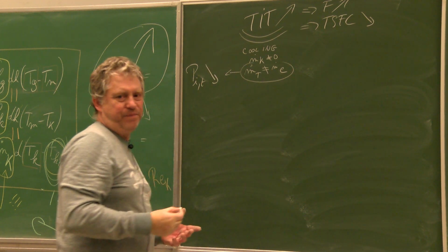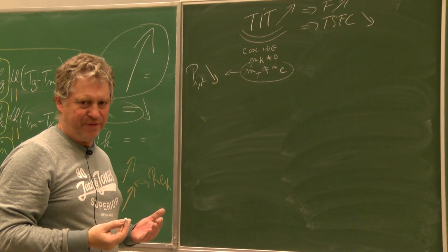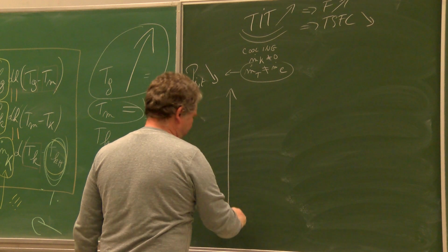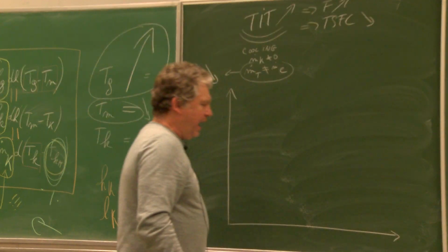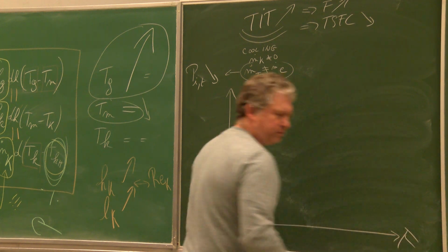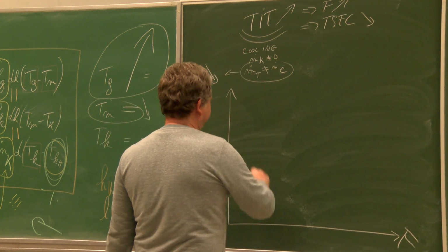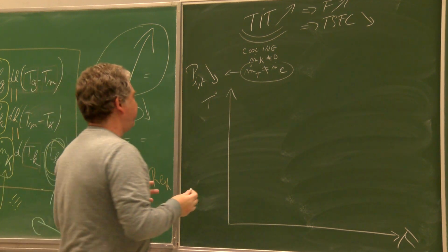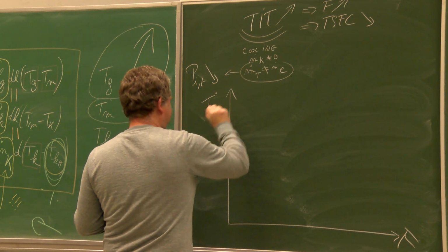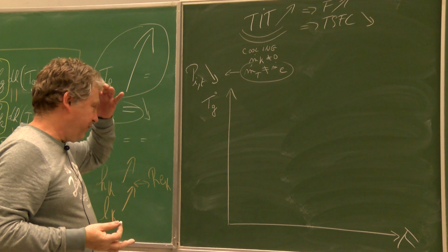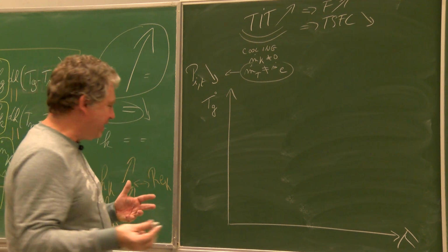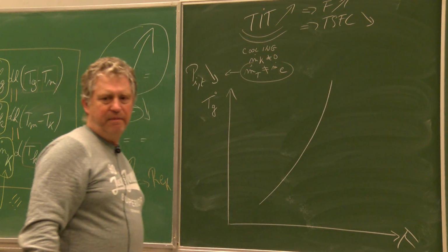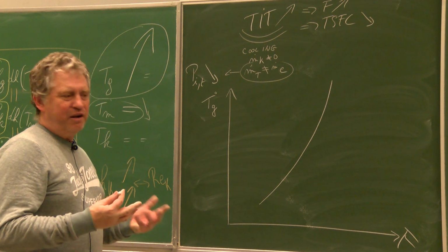The TIT, the power available on the turbine shaft. And how can you represent the problem? This is very often represented like this. I show you here the thrust, and the thrust as a function of the temperature. Which temperature? This is the temperature of the gases, so let's say the TIT. This is a curve that is something like this. Okay? If you increase the TIT, you increase the thrust.